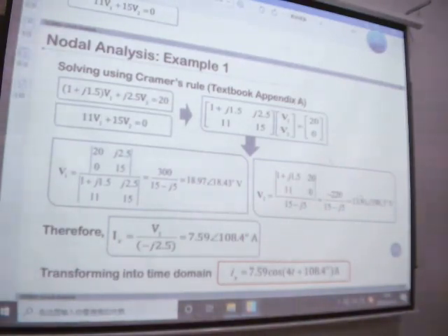But here we should notice that when you do this calculation, the value will be a complex number, and you need to transfer the complex number to polar coordinates. This one is not polar, this one is complex. We transfer it to polar coordinates, and then we get the amplitude and the angle. How to transfer it?